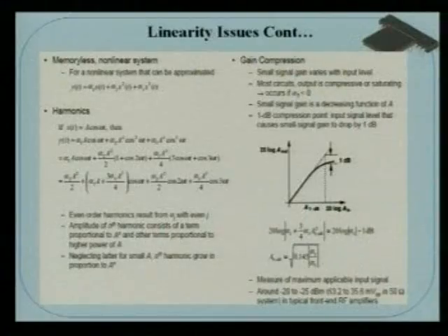Now what does it mean, that harmonic content? If you look at the power conservation, whatever power is fed to my system is through my signal, right, and the DC biasing. I am not giving any extra power. So what is the significance of that plot? This is my input signal amplitude, for example. This is 20 log, so it is a power, okay, and this is the output. I am plotting it. If it is a linear system, what would happen? At 0 it is 0, and it would go linearly. But what happens? It drops.